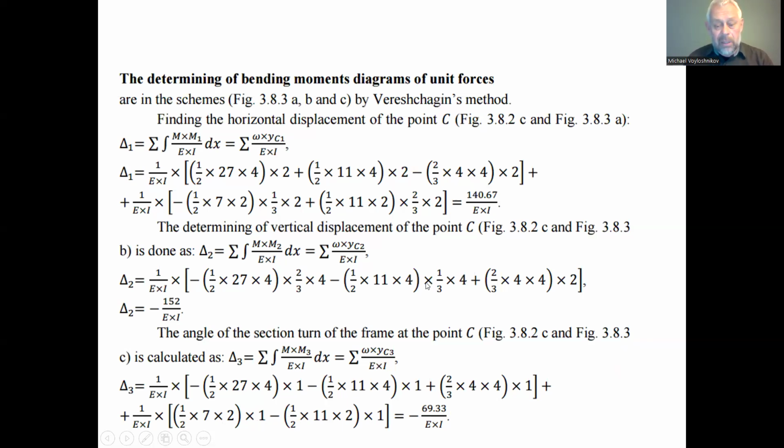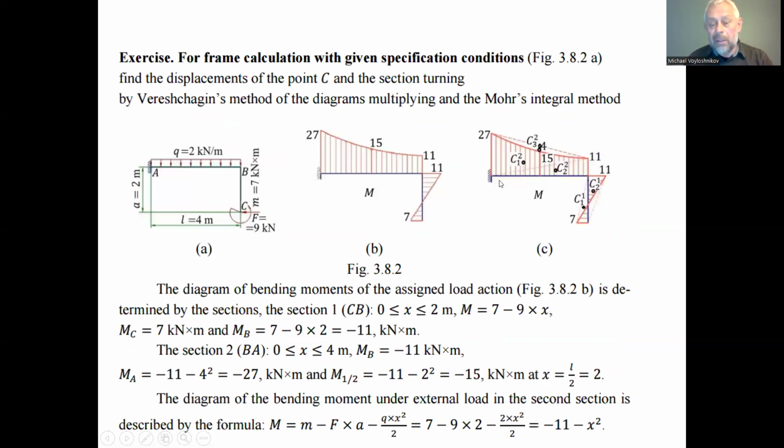And for the second one, the triangle in the decomposition of the bending moment diagram for the AB element of the mechanical system, its location on the AB element is 2/3 part of 4 from the point A and 1/3 from the point B.